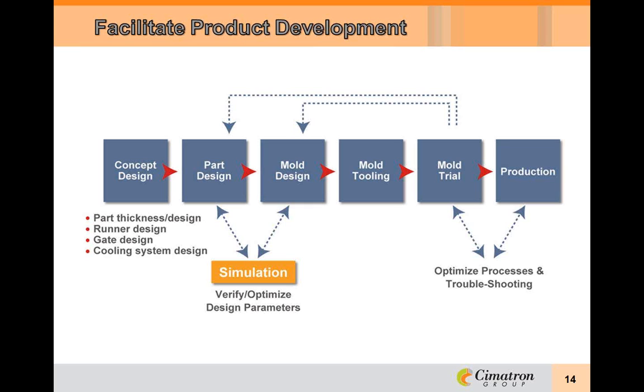In the mold design phase, the design is further refined by adding molding considerations. Runner system and gate are designed according to the process dynamics simulation. Cooling system is optimized to shorten the cycle time and improve part quality. The molding trial on the computer is possible before the actual molding trial is ever conducted. In this way, mold construction has not begun until the molding trials on the computer meet the requirements. The interrelation of part design, material selection, part performance, and processing is all taken into account. Modification of part design and mold design is flexible and concurrent.